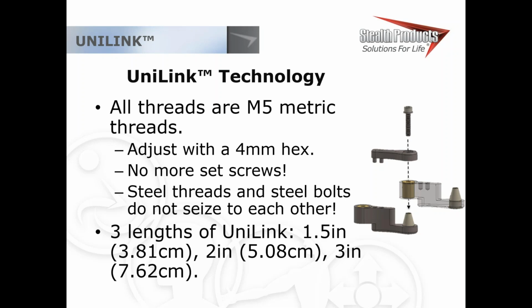So now we eliminate anti-seize, we have a steel bolt going into steel threads, everything's happy, it tightens down really nice, holds rock solid, and best part of all is no more sparks and gunpowder and smoke and stuff when you loosen. I don't know how you're supposed to tell that it's loose now if it doesn't explode at you, but everything's nice and clean, easy to deal with there.